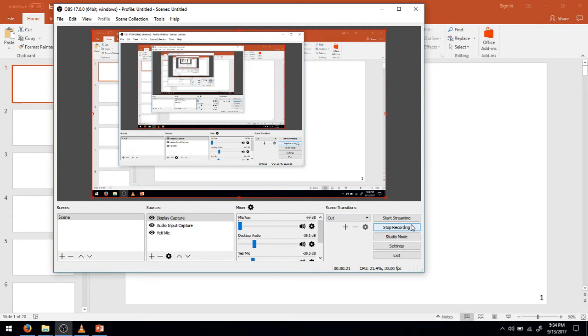Okay, for this portion of the second lecture I have a few objectives. First, I wish to identify types of steel structures. Second, I wish to describe types of loads resisted by these structures. Third, I wish to describe and discuss the difference between braces and moment frames. And fourth, describe diaphragm action and use various concepts to describe and determine loads on building frames.